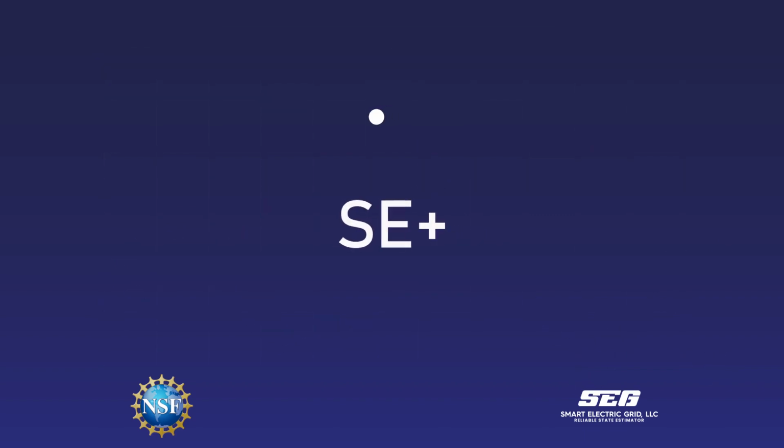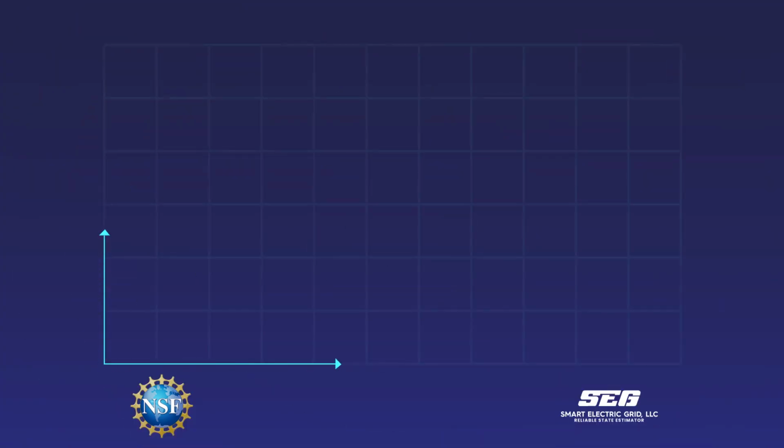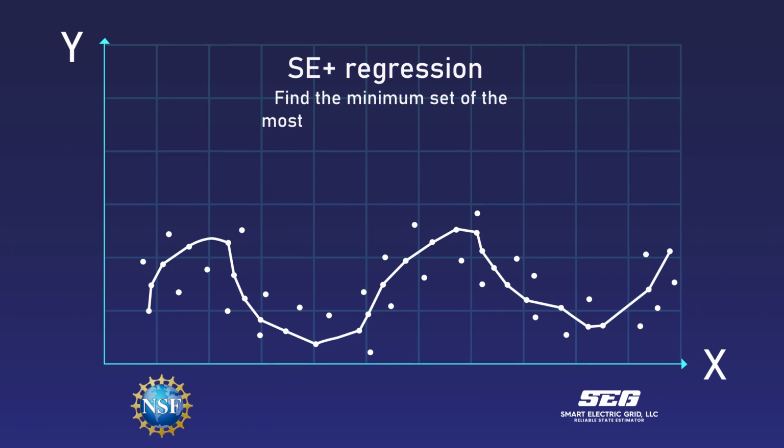SE Plus is a new regression approach developed by Smart Electric Grid, LLC, with support from the National Science Foundation SBIR program. It aims to select the minimum set of the most consistent measurements. The entire system is then solved by the selected minimum set of the most consistent measurements. This approach is different from weighted least square regression and other regression algorithms.